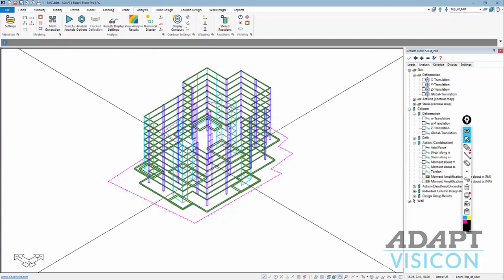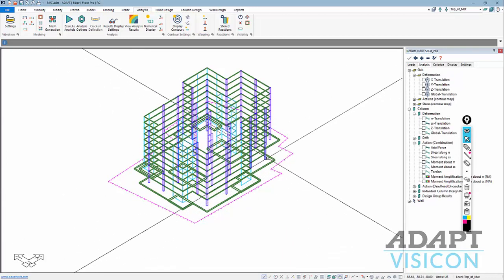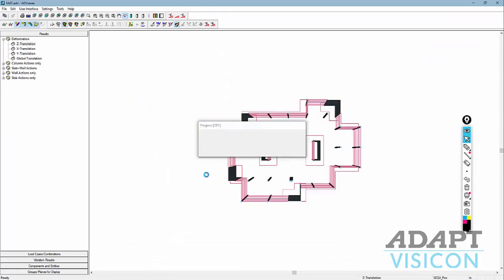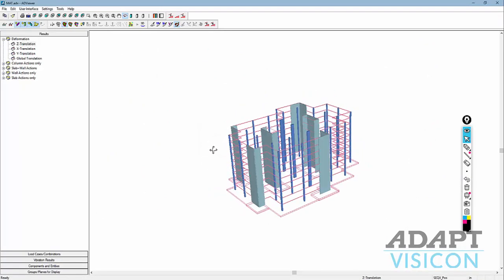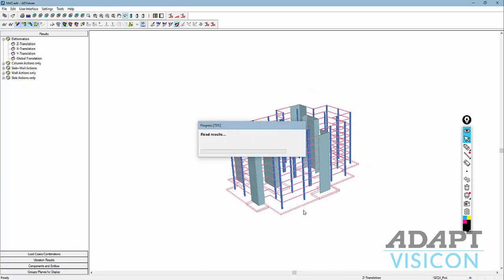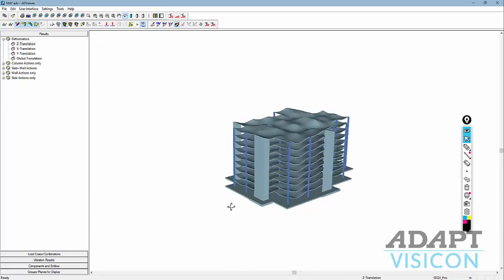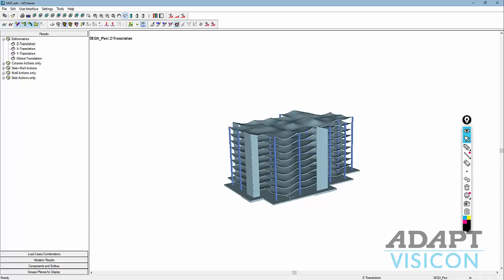so once that's done, we've obtained reactions at the base of the structure, but if we look at the deformed shape again, because we use substitution, if I just look at the vertical deflection, we're going to have no displacement at the mat. The mat is essentially ignored when we run the model with substitution. However, we can now apply the springs or the mat with springs and use the reactions obtained from this first solution directly on the mat.